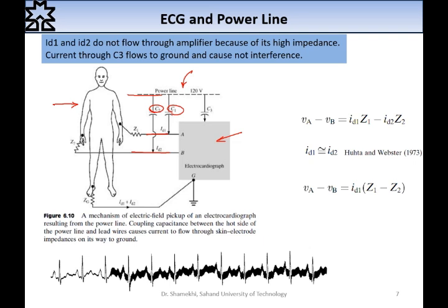We don't have any real capacitances here. C1, C2, and C3 are the model of the capacitive behavior of the environment. But these model capacitances affect our system, affect our wires, and therefore we should model these bad effects.